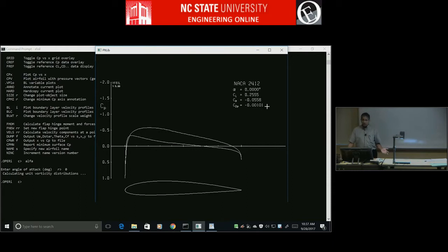And really CD pressure should have been 0, but this is a numerical method, right? So there is going to be a small amount of CD. I'm kind of surprised it's this high. But anyway, even in inviscid flow, it will end up calculating a CDP because it is a discretized airfoil and a discretized pressure distribution. And just like in homework 1, you saw that even in inviscid flow, you would get a small amount of CD, and that's what this is.